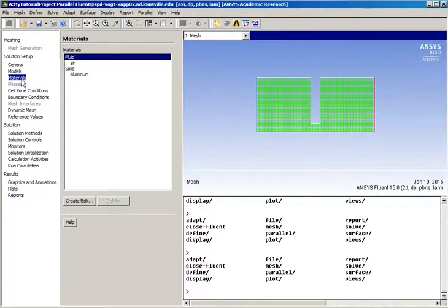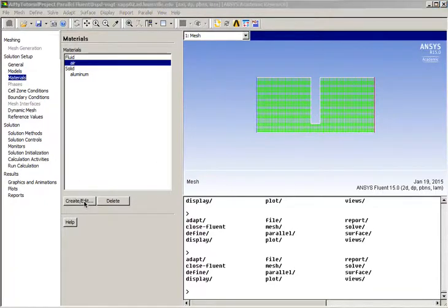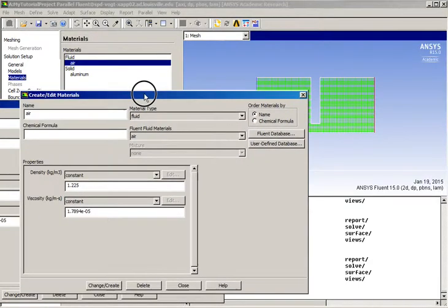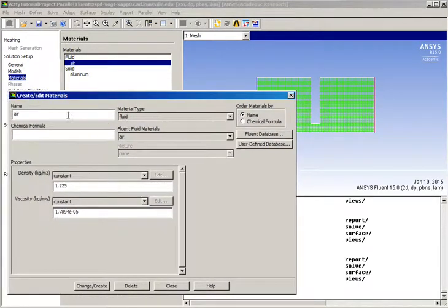The materials pane, now this one we have to modify. We want to have water, and since we chose viscous laminar, okay, we can hit the air that it defaults to for the material in this green area and edit that and make it more like water. Okay, let's bring this into the place where you can see it. Since it's such a limited simulation, we're not doing thermal transfer or compressible things or anything. We just have to enter the material's density and viscosity. And you can look through the Fluent database and find these things for water.